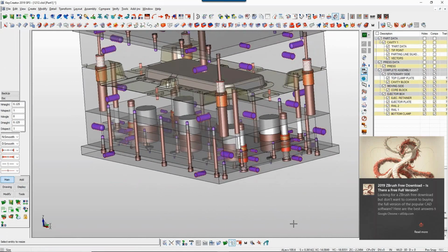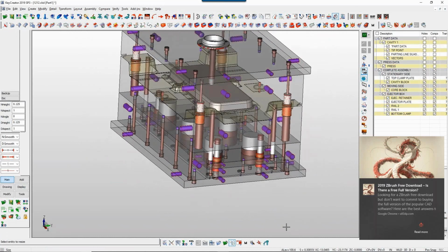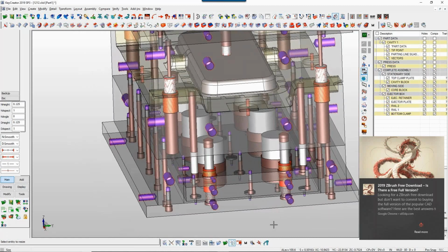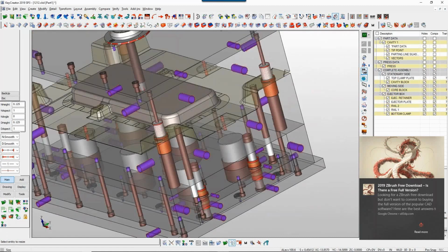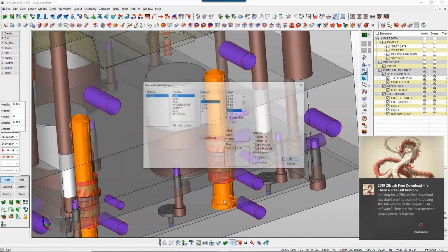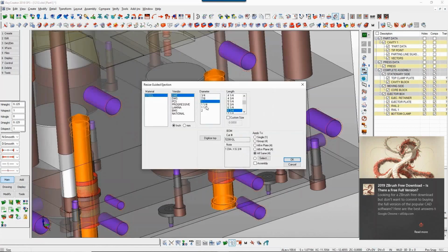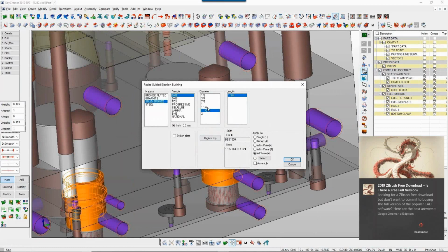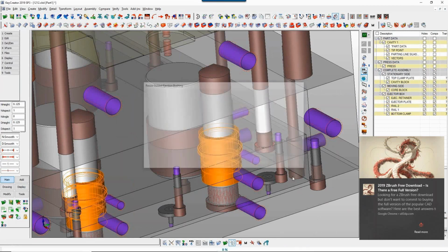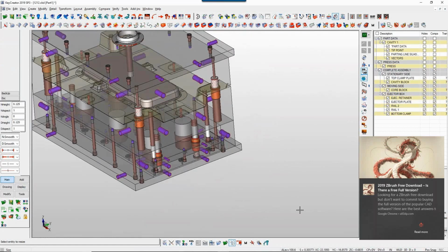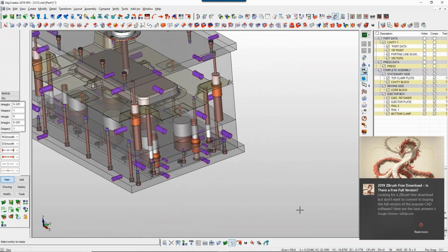Okay. Sizes and stuff, once again, utilizing industry best practices. So the sizes are generally very good, and you will find it would be extremely rare that you even need to manipulate those sizes. Okay? What we are going to do, though, is manipulate one just to kind of show you how easy it is. So if I want to change that ejector guide to, let's just go to 1.5, just so it's very drastic. I'm going to say all plate, we're going to go ahead and change it. You'll see it's much bigger. Okay? So if we want to go back to the 1 inch, we can just click it. So if you want to visually see the difference, it's just quick and easy to do, right? And in that time, the material has changed to the bigger one, then changed back to the smaller one. It knows what to do.